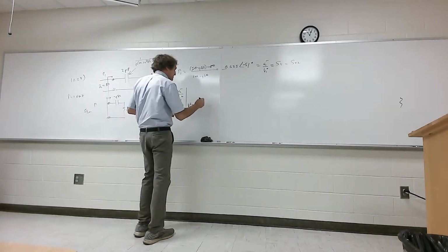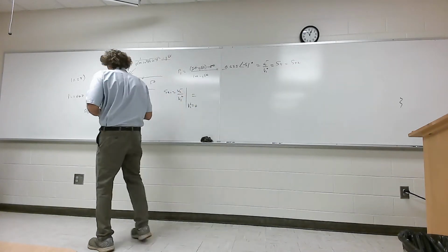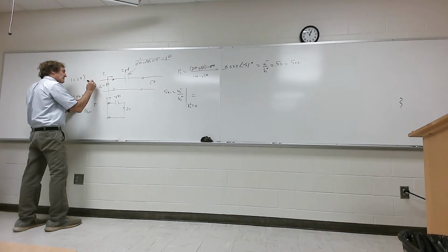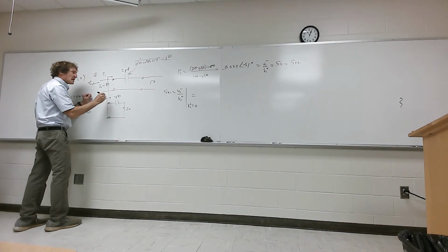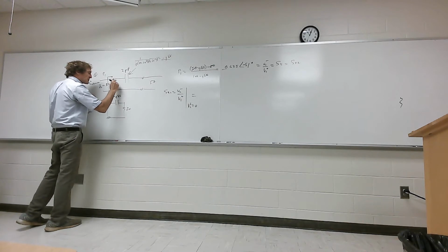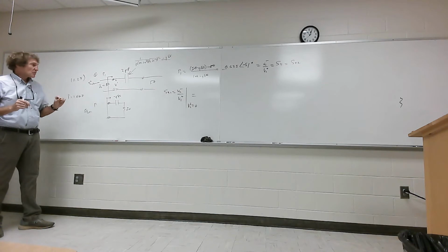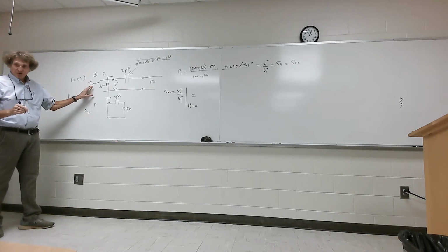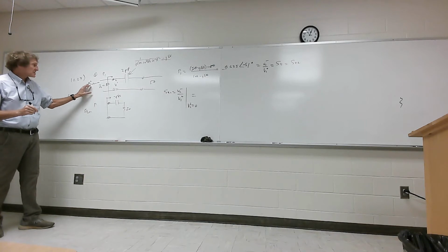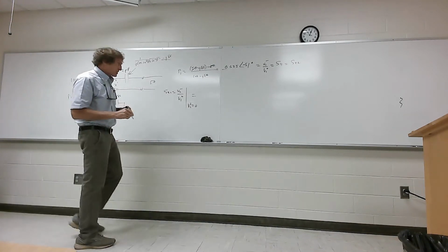Okay, so how do we do that? Well, the first thing we need to do, this is port 1, if we have V1 plus coming in, I need to find the value of what I call V prime there, correct? And V prime is the transmission coefficient times V1 plus. Do y'all follow me? The transmission coefficient is 1 plus the reflection coefficient, times V1 plus. So I'm just going to put it here.